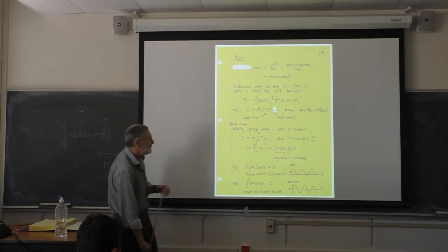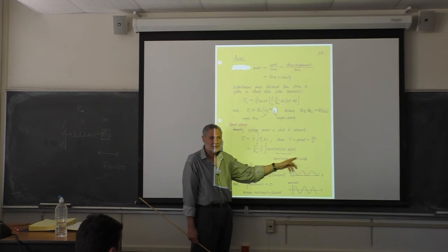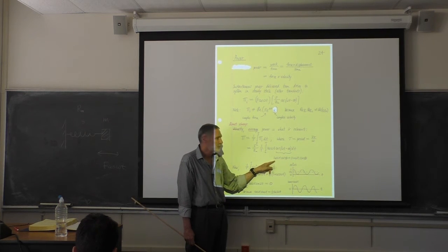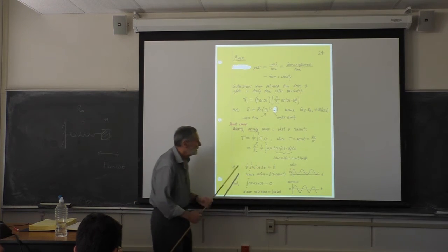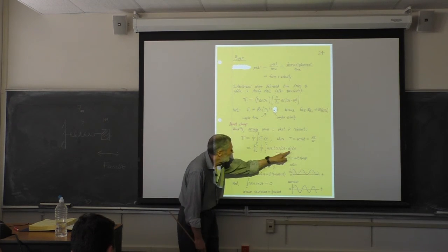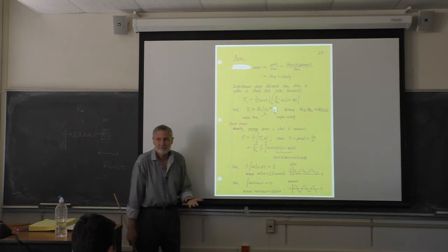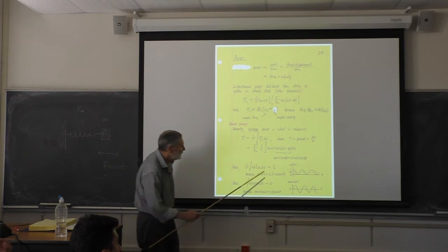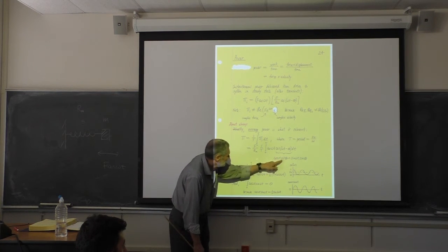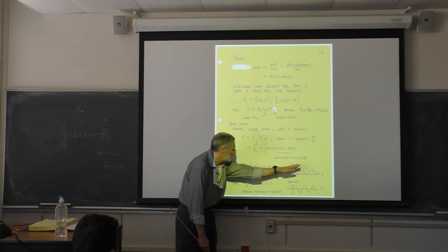So how do we analyze this? Well, the easiest thing to do is just recognize the trigonometric identity. The cosine of a sum or difference of two angles is the product of the cosines and the product of the sines, right? This is just a standard high school trigonometric identity. Now you want to notice here that we're integrating over time. This theta is constant. It's just the constant phase angle of the impedance. Remember, it's capital theta. So these factors right here come outside, and the integral becomes two integrals.